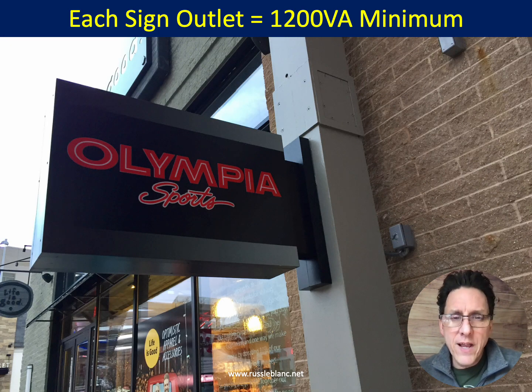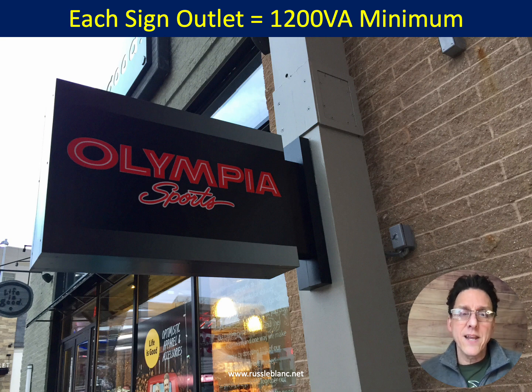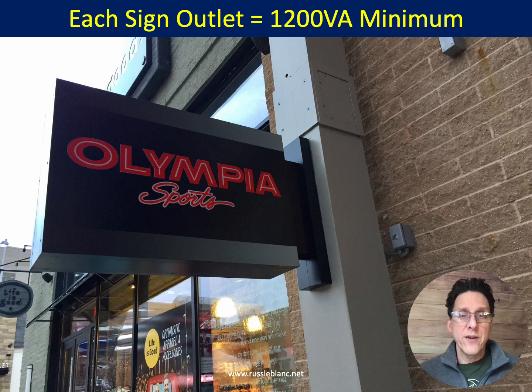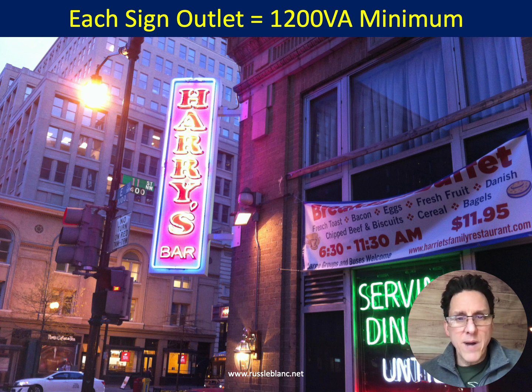All right, and as far as the branch circuit calculation goes, again, 1200 volt amps minimum for every one of these required sign outlets. So this Olympia Sports sign. If the actual rating of the sign is greater than 1200 volt amps, absolutely use that. If it's 2400 volt amps, use that. Don't use the 1200 volt amps. Harry's Bar. If that sign is greater than 1200 volt amps, then use that information.